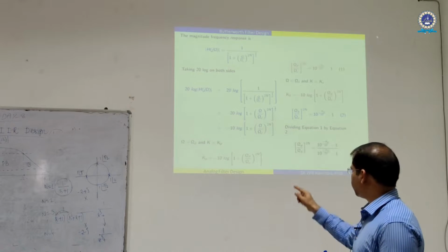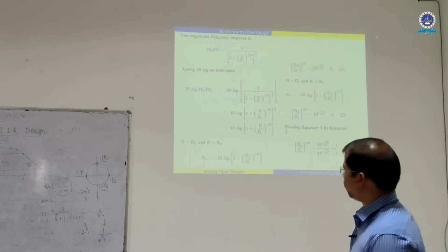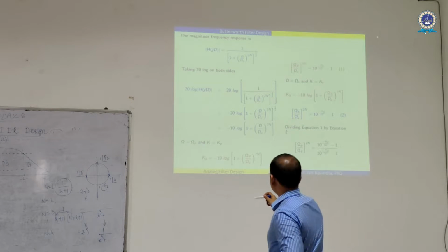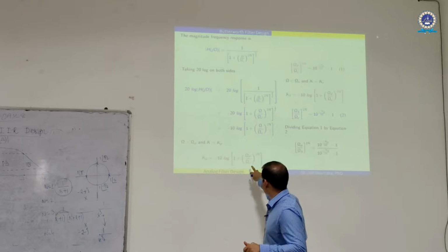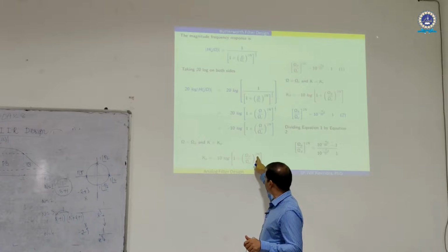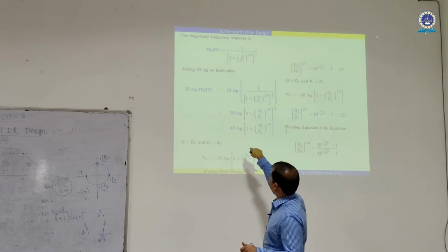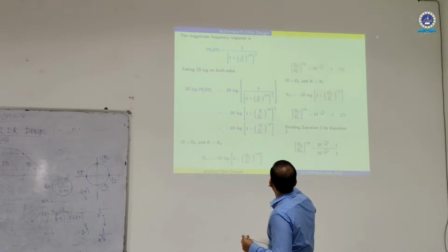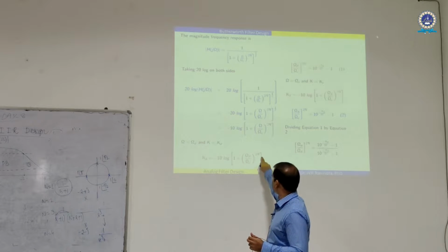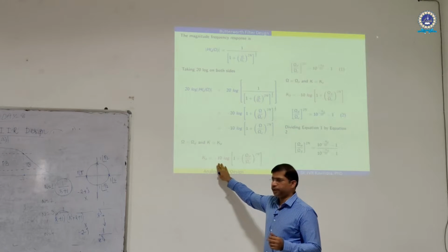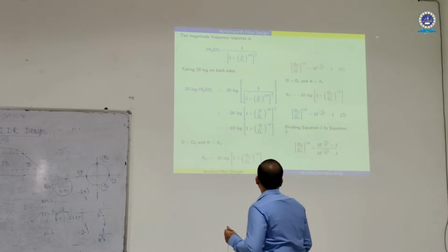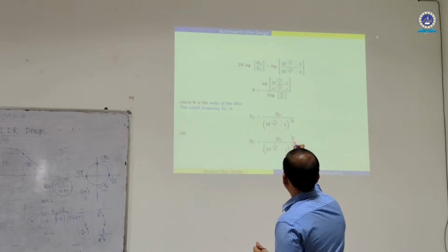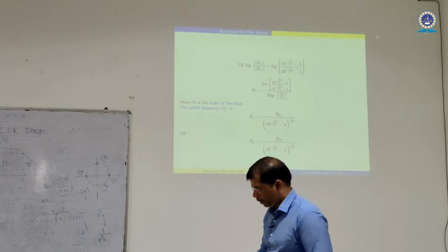So here these are the equations that I have derived. Of course, all these things are available in the open book. And this is the Kp value. Okay, and passband frequency will be there, and this is the cutoff frequency whole power 2n. So n we have to calculate first of all to do this. From the fundamentals, we need to calculate the n value. That n value we have to substitute here, and then you get this Kp. And similarly the Ks value. And that is the n value if you look at that.